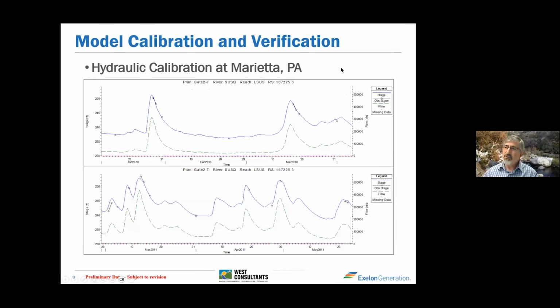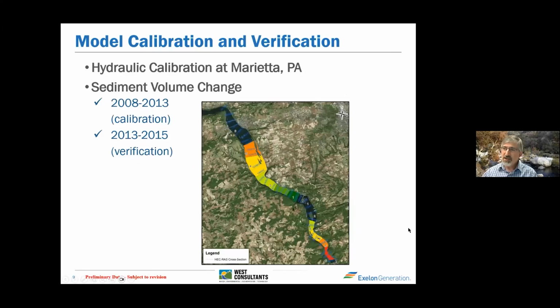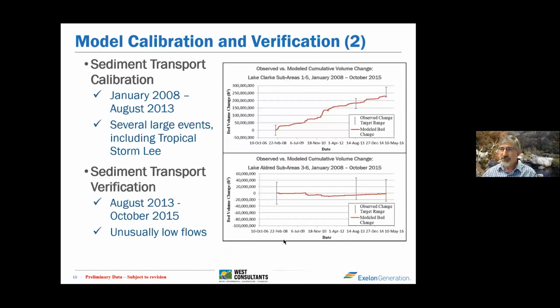So I'm skipping through this very quickly, but we did hydraulic model calibration. I'm sure Stanford would be happy to hear me say this, but as he said many times, and we both heard from Tony Thomas, you really can't have a good sediment transport model until you know you have the hydraulics correct, right. And so here's a calibration that we did as part of the modeling. We actually, based on the collected data we had for calibration, we had a bunch of different ranges within these reservoirs. And we had one period that we used for calibration and another period for verification, where we compared the model results to what was measured based on the field data.